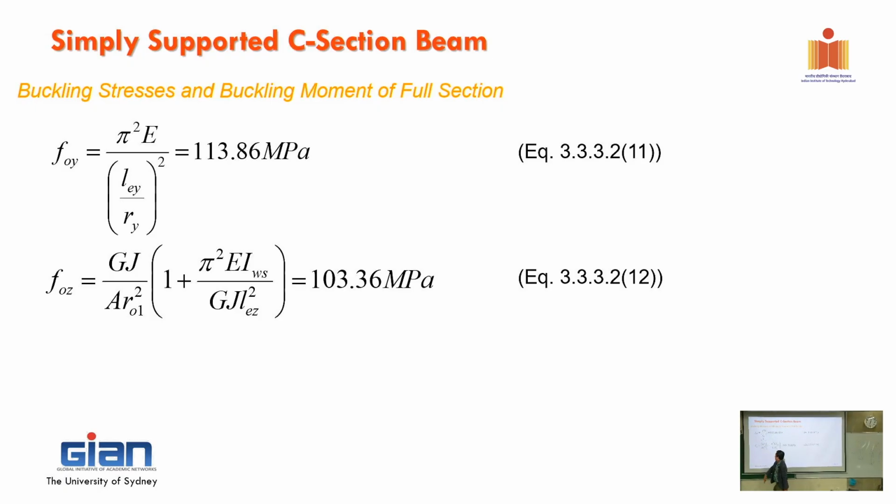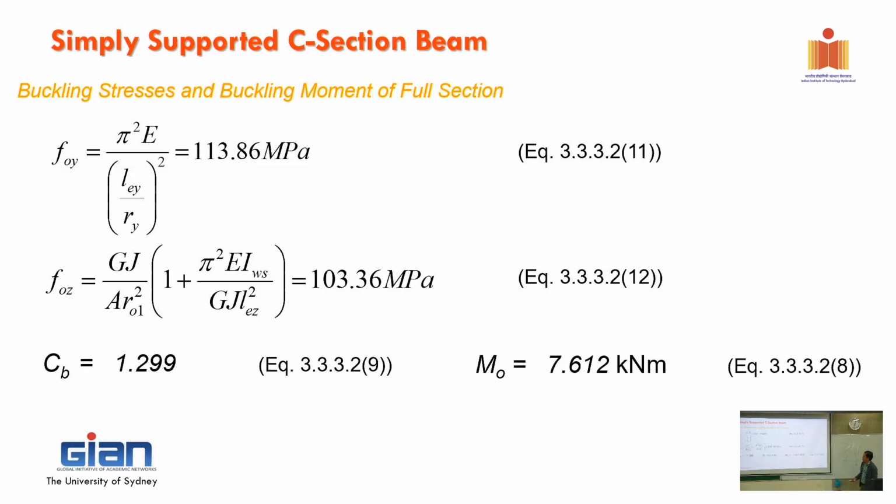So that is the first one, and this one as well, related to the warping, okay? And that one will increase again, depending on the boundary condition. Right, so in the equation, you've got all that you want. You've got L_ey, L_ez, you've got everything. You plug into the equation, you get F_oy and F_oz, and then you can calculate the elastic buckling moment, simply, okay?